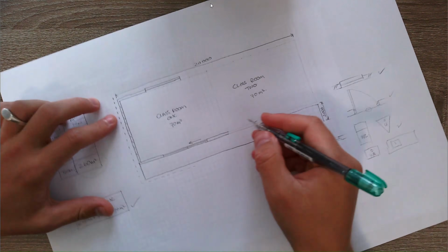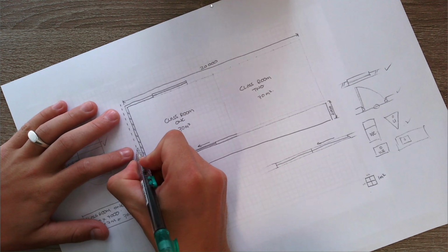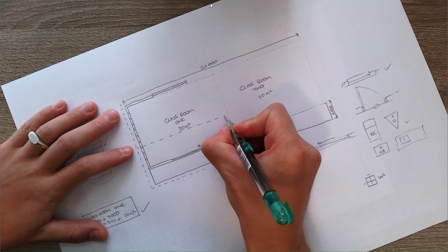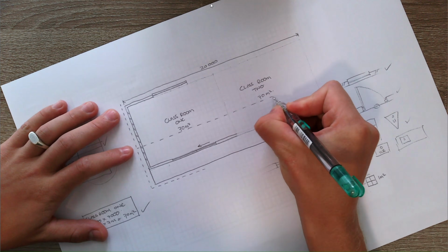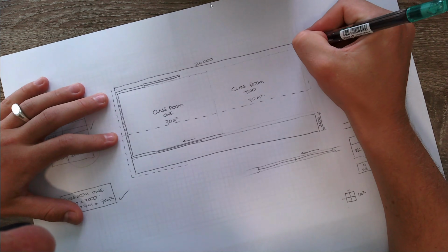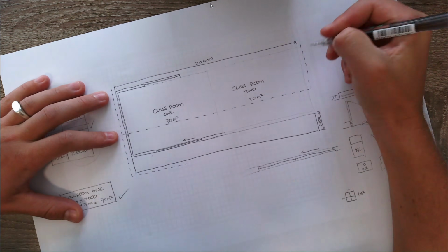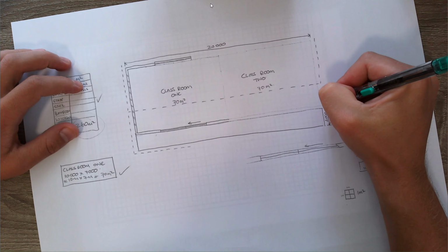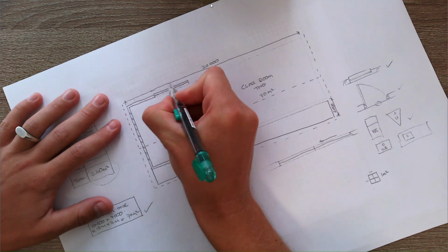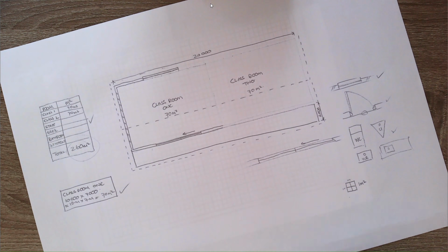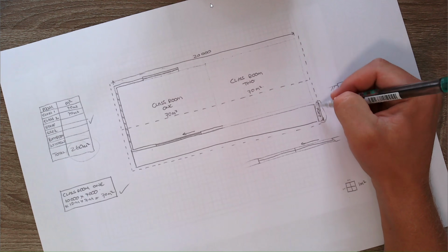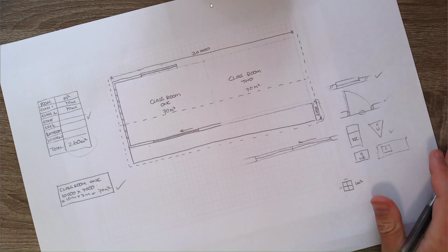You'll do the same on this side, and then wherever the pitch is, the highest point, you will put that in on the floor plan as well. Everything nice and freehand. If your roof runs in this orientation, you put it in according to your design. So don't forget to put in the roof detail. Just make sure that your dimension lines do not lie on top of your roof detail.